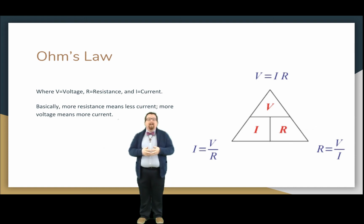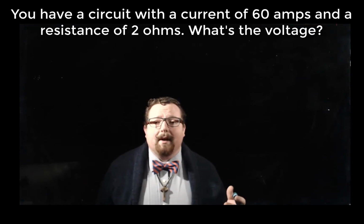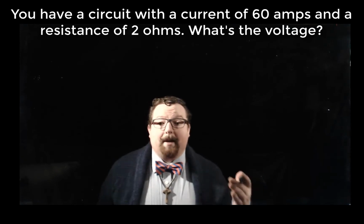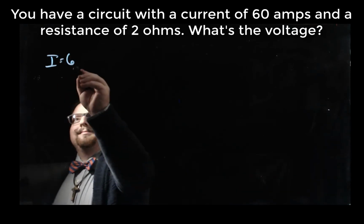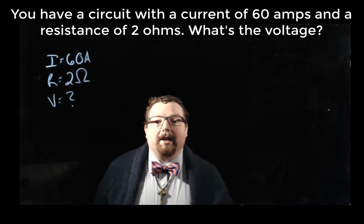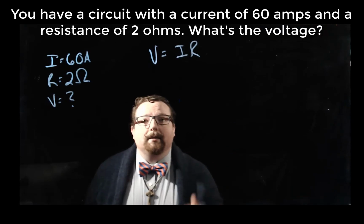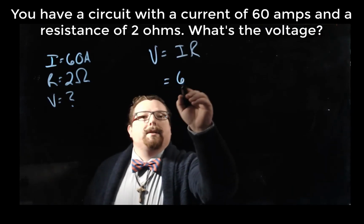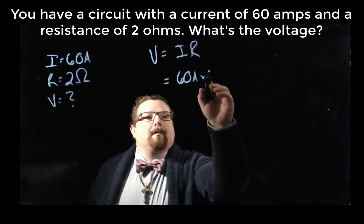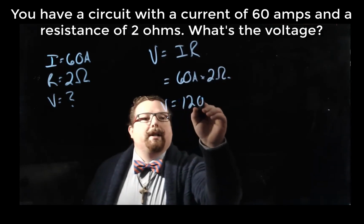So let's do a few example problems. Okay, so our first problem says that our current is 60 amps and our resistance is 2 ohms, so find the voltage. First step is to write down what you know, and then write down the equation you're going to use. Since we're looking for voltage, we'll use V equals I times R. Plug in our numbers, and you get that the voltage is equal to 120 volts.